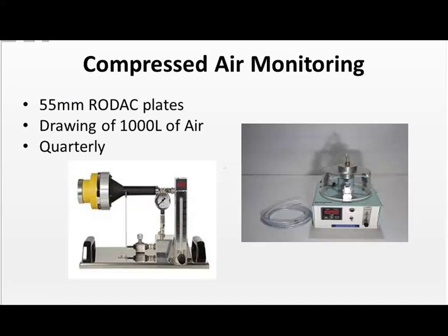We also have compressed air monitoring. We said we monitor these for particulates. We also monitor them for bioburden as well. And what you're seeing, the machine on the right, is called a Matson-Garvin machine, and you're going to pour a media plate and set it on a rotation device up under that clear hood of that machine, and it's going to be hooked up to the compressed air, and it's going to blow compressed air down on that media for a certain amount of time.